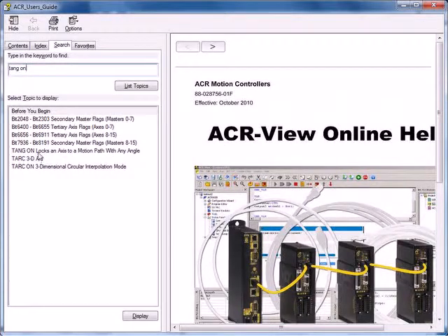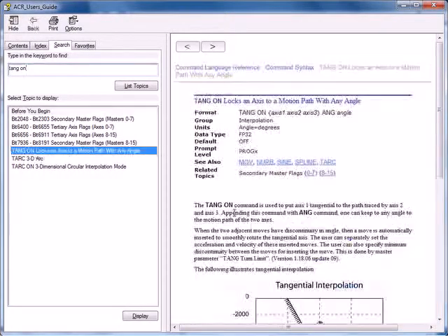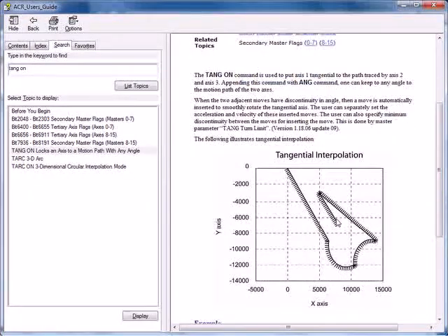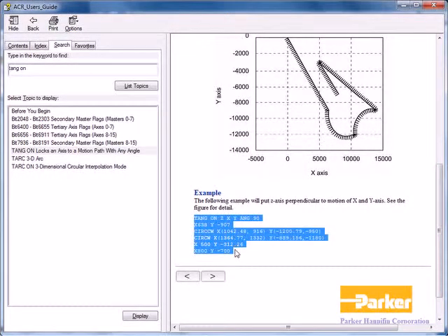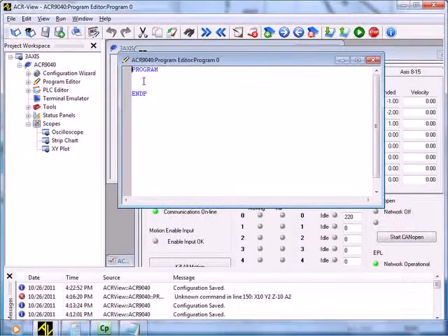This starts at ACC 100, DEC 100. Let's set the velocity to 30 so it'll proceed fairly quickly, and set the jerk to 50. And then after the tangential move is done, I want that to turn off. After it's complete, go ahead and download.